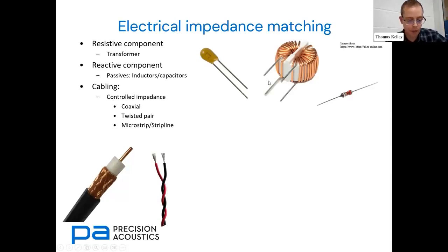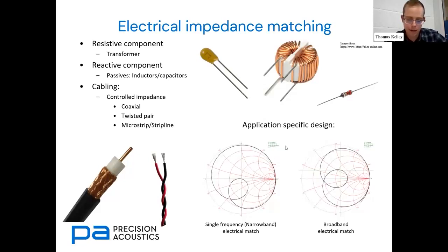So being a frequency-dependent property, the impedance cannot be tuned to a perfect match at all frequencies at any one time. That's a key point to remember. As you can see here on these little Smith chart pictures, which are normalized to a 50 ohm central point, we can choose from a narrowband match where we have a single frequency selected to be matched to 50 ohms exactly, at the expense of all the other frequencies, which are quite a long way from 50 ohms.